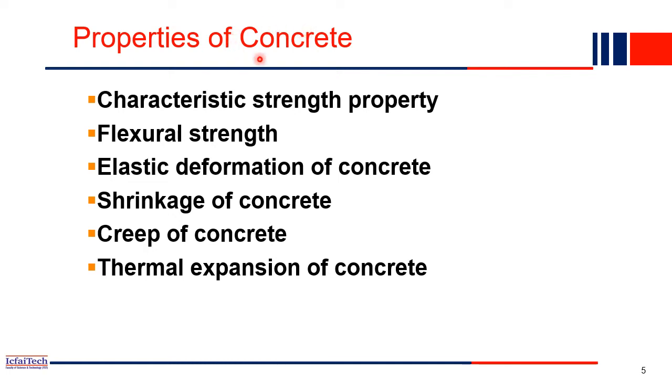But there is a limitation in concrete. Concrete is very good in taking compression force. So as long as you apply compression force on a structure made of concrete, the concrete can take the compressive strength before failure. Whereas concrete is very weak in tension. In a structure, some parts will be subjected to compressive force, some parts will be subjected to tension. So concrete is very good in compression. Anywhere the compression forces are acting, there we will provide the concrete.